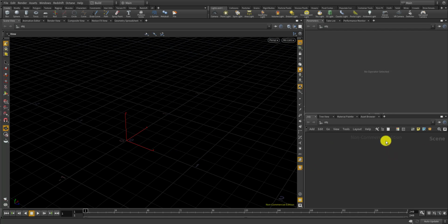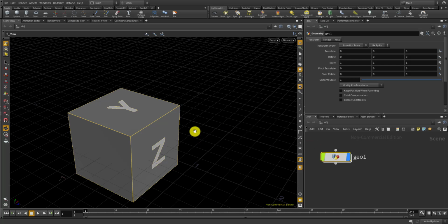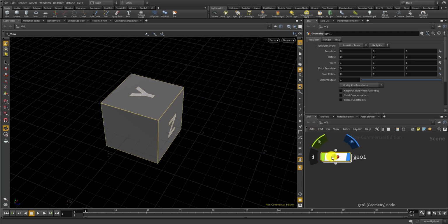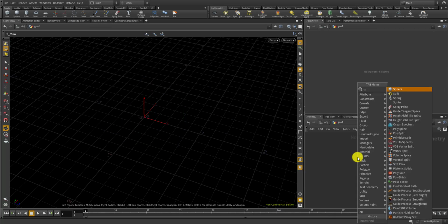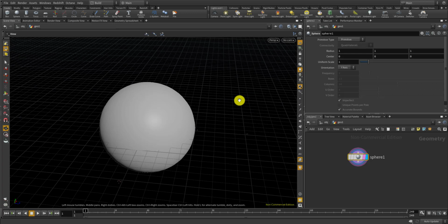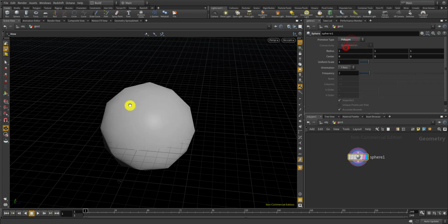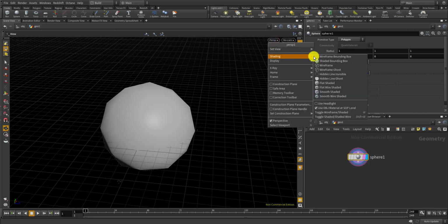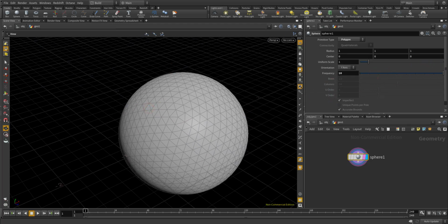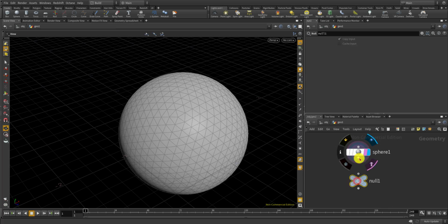First of all, let's make a base geometry for the frosting. For Anton's examples, it was made on top of a grid, but for this example, I would like to make it on a sphere, so that if you change the sphere to any kind of 3D geometry, it could be reused for 3D frosting. So as a typical shape, let's use a sphere as a template. And I'm gonna set the frequency to 10 to make it smooth enough. Let's name this base geo.